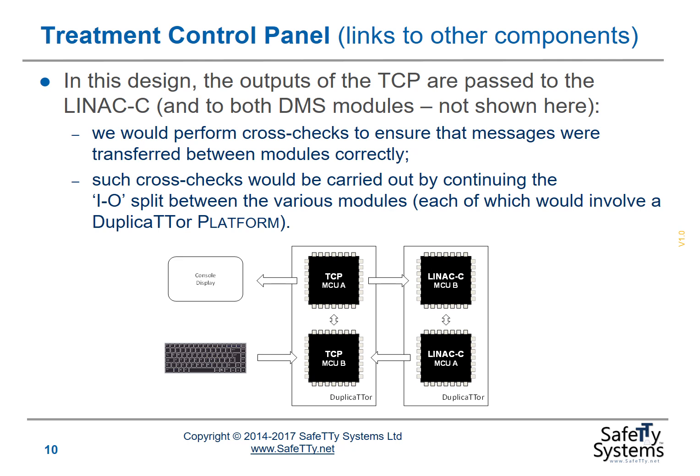So the original message might come in and say, do X. The first microcontroller would say, I think it says do X. The second microcontroller would say, I think it says do X as well. If the two agree, then the second microcontroller sends a message back to say, I received the message do X. So we continue confirmation through this process with multiple cross-checks happening between the microcontrollers to ensure that we obtain the required behavior.